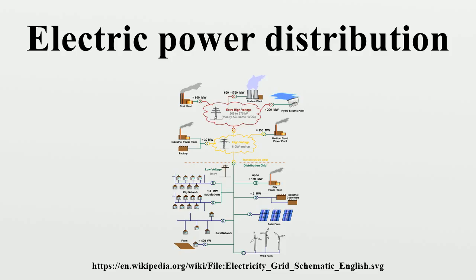High-voltage DC is used for transmission of large blocks of power over long distances, for transmission over submarine cables for medium distances or for interconnecting adjacent AC networks, but not for local distribution to customers, because the maximum voltage a generator can produce is economically limited by the insulation of its windings.